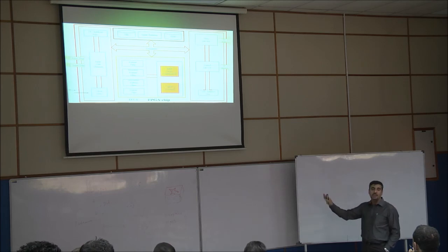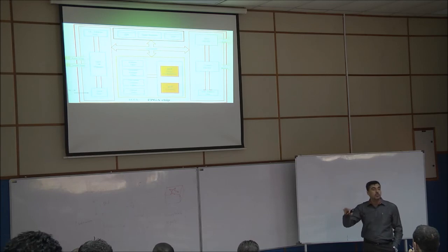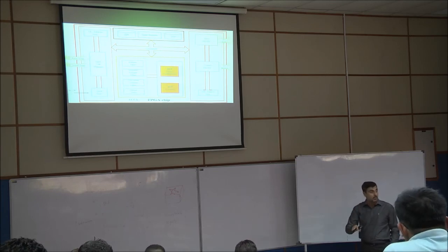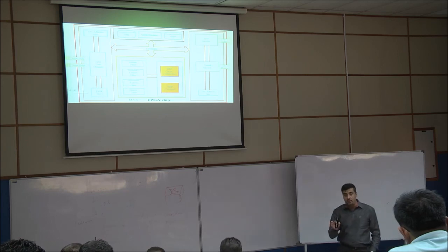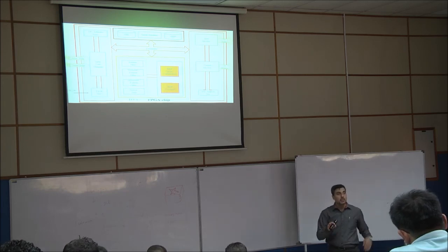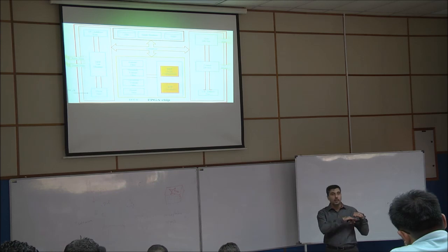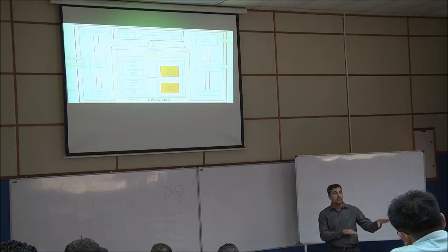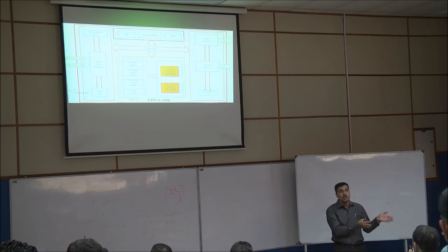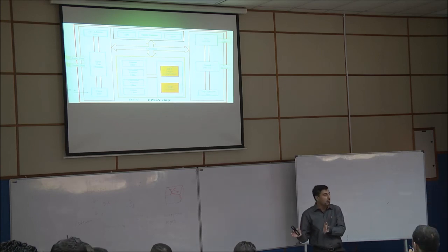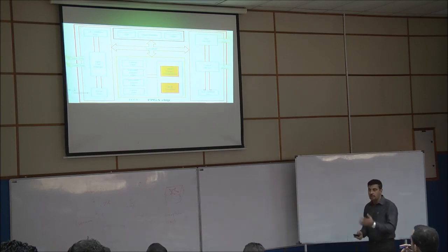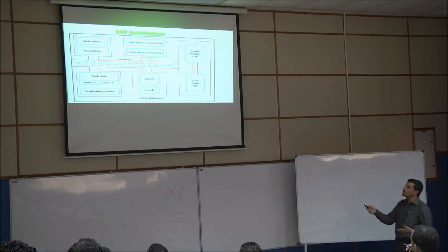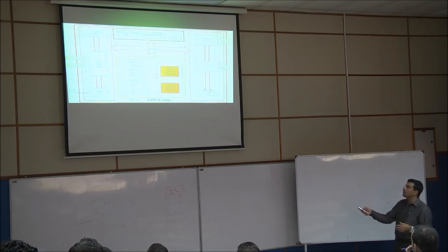An architecture like this cannot use one frequency. We have to use multiple frequencies, multiple clocks as we call it. And a multiple clock design system is very complex, because you don't have one clock supporting every module. You have different clocks. That means one of them works at 100 meg, the other at 200 meg. One of them works at 10 nano, the other at 5 nano. You see the difference? So synchronization is more complicated in this system. This is the processor architecture.